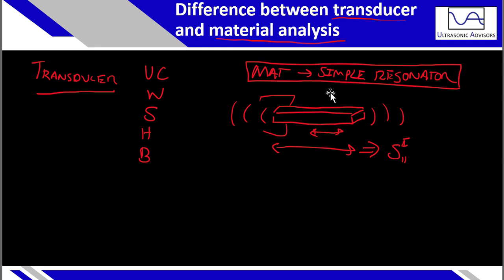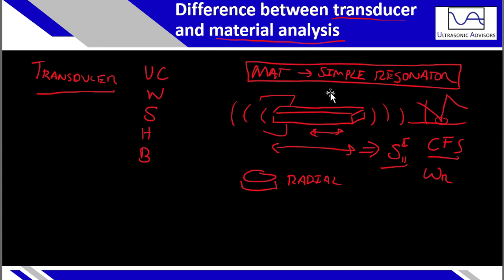And not only related, it will have a closed form solution relating the natural frequency measured, through the minimum impedance, to your material property. So by using simple geometry such as a bar, which is long in the width direction, or if you use a thin circular plate, which has what we call radial vibration, or if you use a bar which is longer, and the top and bottom are the electroded portions here.